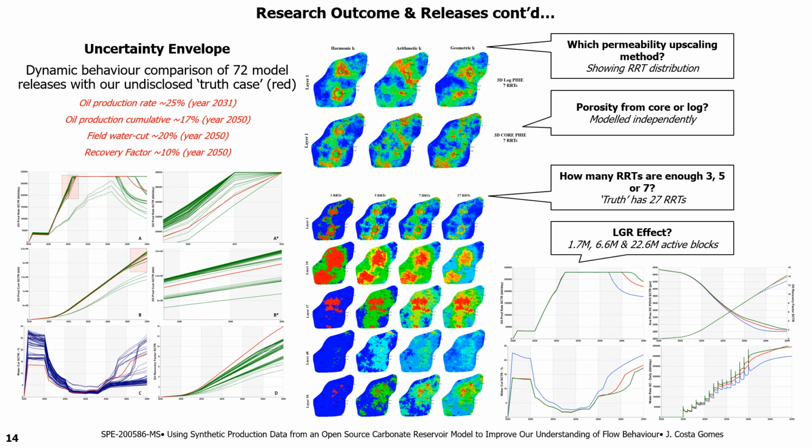And the impact it has on well production rates and water cuts is actually quite remarkable, and it's good for learning purposes. Because the reservoir is so large, by reducing the grid sizes, you reduce the numerical dispersion. In this particular case, if you go from 1.7 to 22.2 million grid blocks, you increase the plateau by about 4 years. And all of these models, and these are just preliminary results currently to show the uncertainty envelope, will hopefully aid our industry in many aspects.